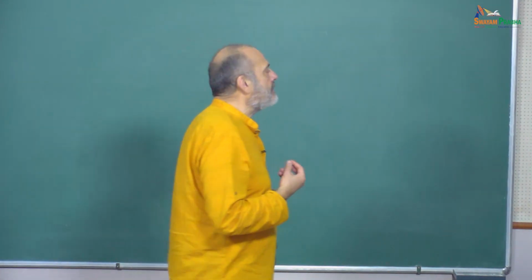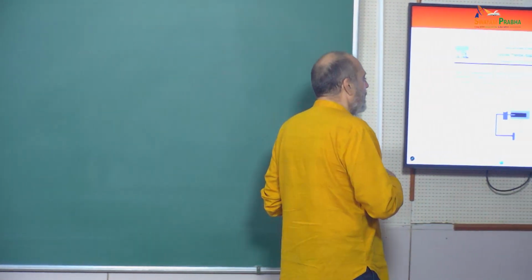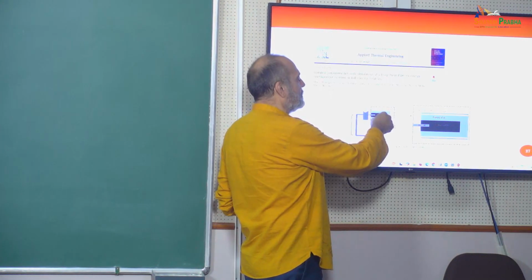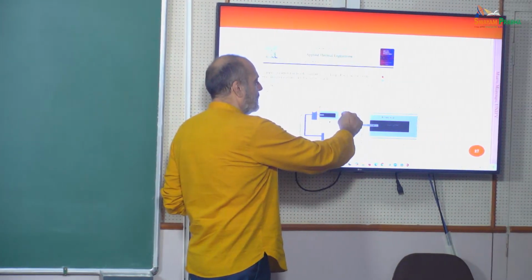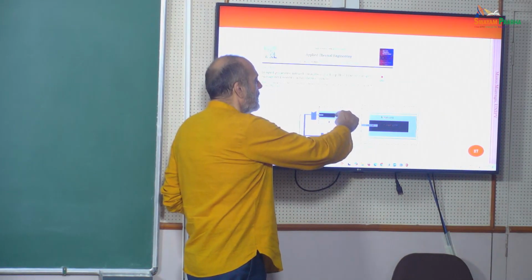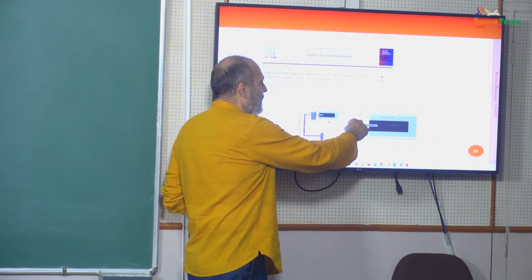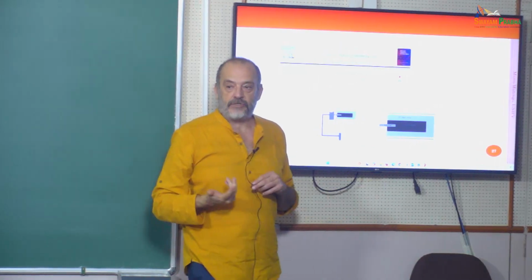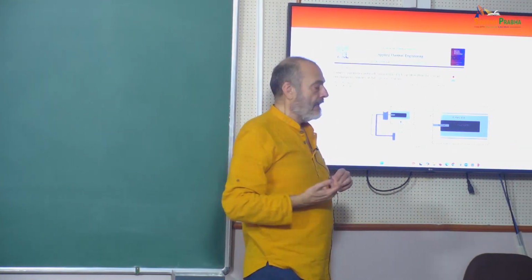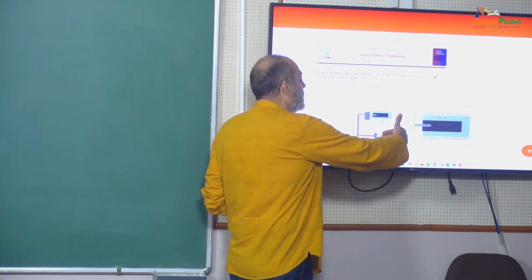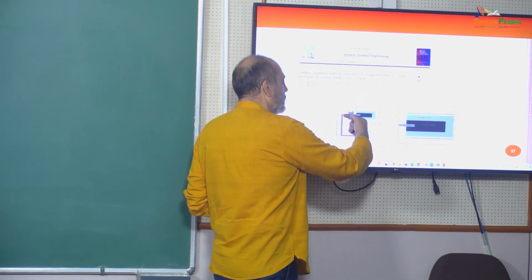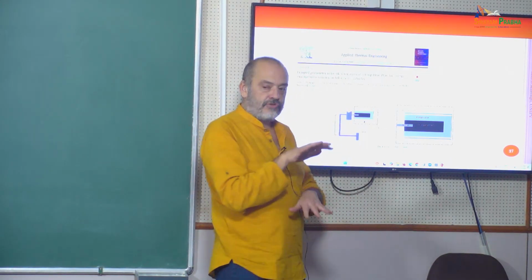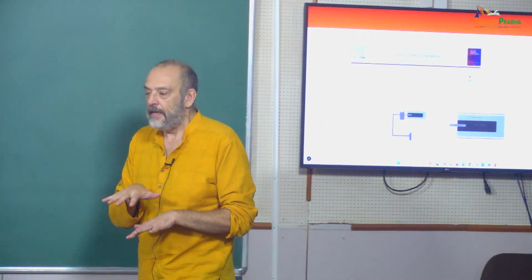What is happening here is that the vapor that is formed is going to push, as a high pressure, other vapor in this line, which arrives in the condenser, and here we have the formation of the liquid, okay? And the liquid is pushed in the other direction until a compensation chamber, okay?